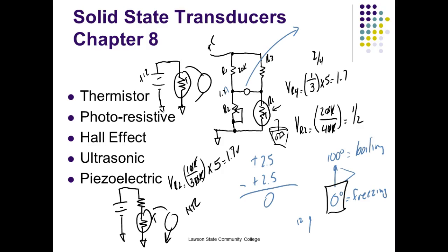So we use devices in scales. They're called strain gauges. They vary their resistance with weight. Well, by George, I want to know what zero weight is equal to, right? So how do they set zero? Well, they set zero with a Wheatstone bridge. Once I've set zero in a Wheatstone bridge, we get a voltage out of them, right? You understand, because we put that fixed zero in there. Now I get a voltage that represents weight.